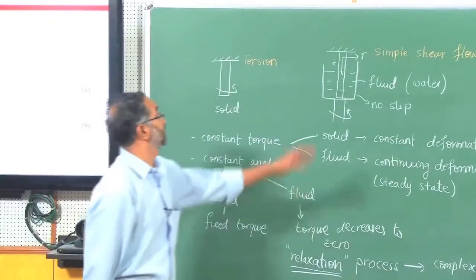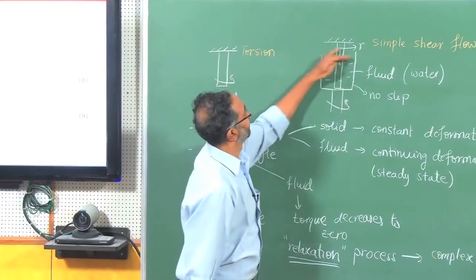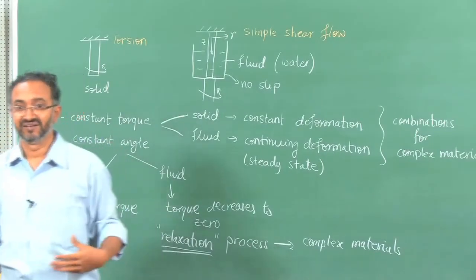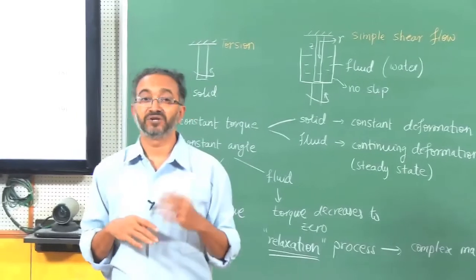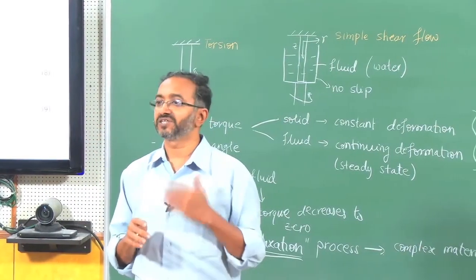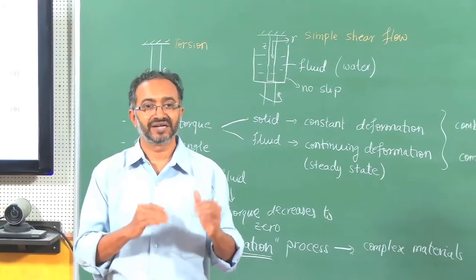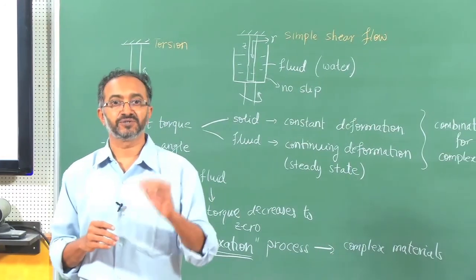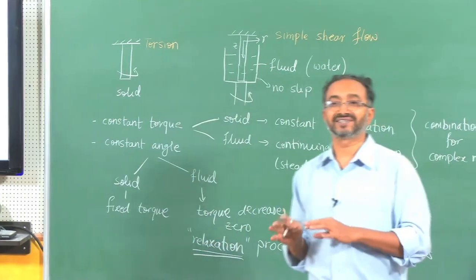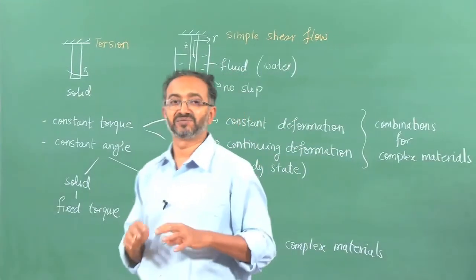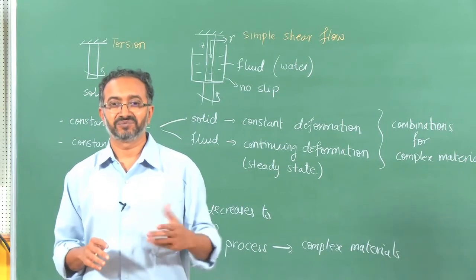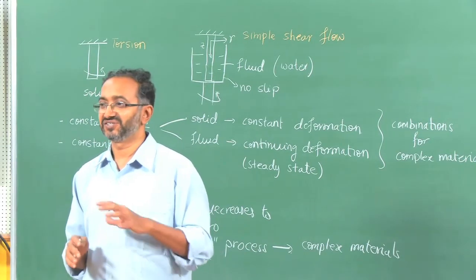We assume, for example, that the rotation rate is small enough that we do not have any of the features associated with very high inertial forces. That is an important assumption in many of our rheological analyses. We will always assume that viscous forces dominate and inertial forces are negligible. In other words, the Reynolds number is small, because this will help us in understanding the contact stresses and the deviatoric stresses that arise in the material, because that is our main goal, to find out the mechanisms by which contact forces and deviatoric stress are generated in the fluid.